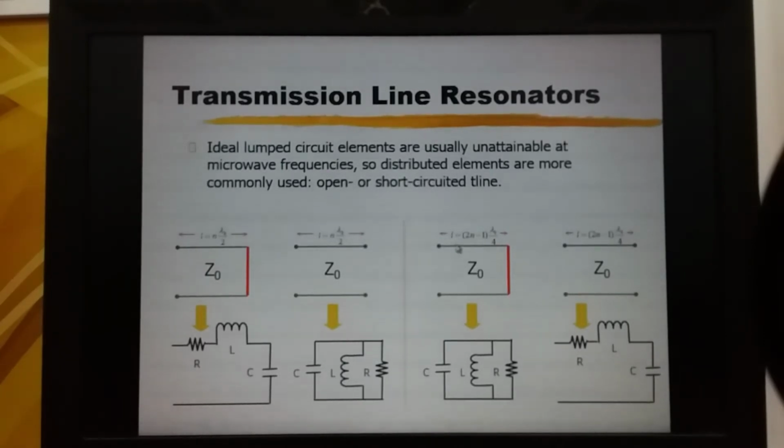If the length of the transmission line is a quarter wavelength or odd multiple of quarter wavelength, the situation will be different. This time, if the quarter wavelength transmission line is shorted at the end, it will be transformed to infinity ohm at the input. This is the behavior of a quarter wave transformer, but this time we have a short circuit at the end.